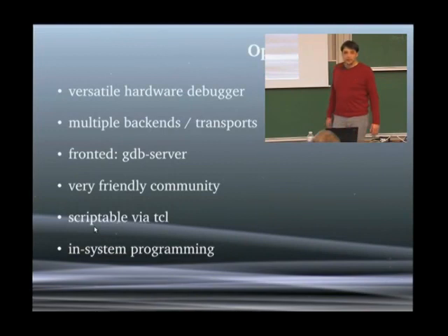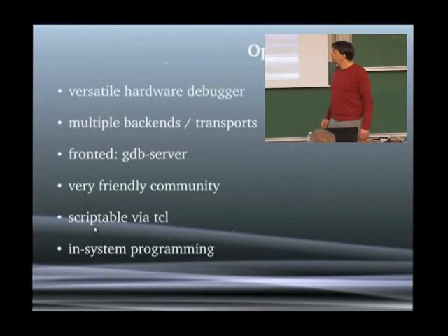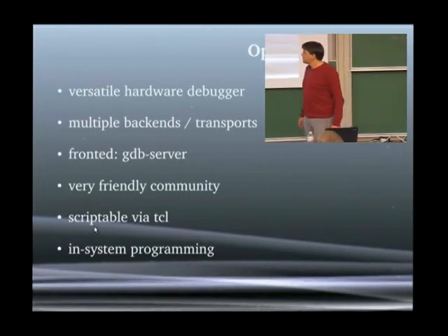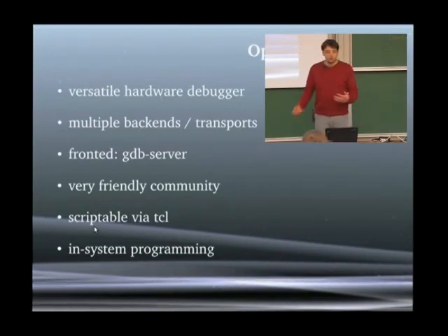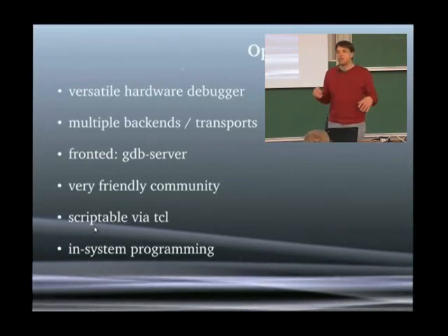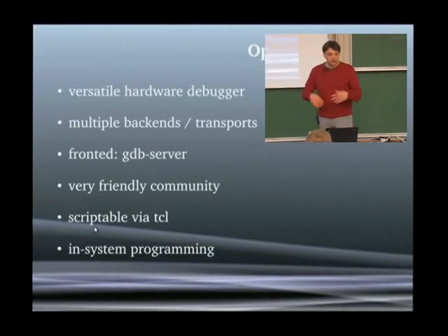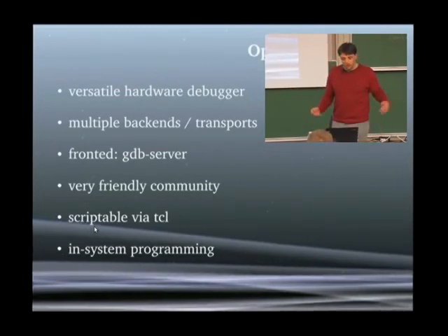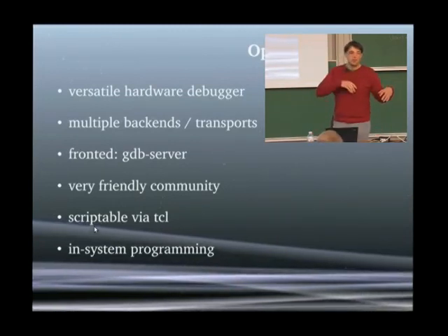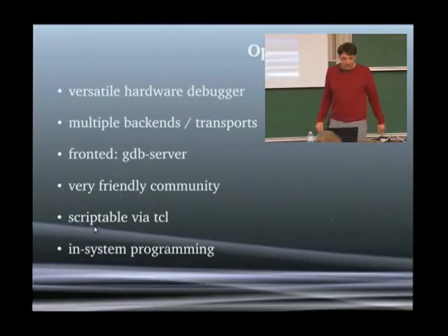OpenOCD's front end is a GDB server, so that's the way QtCreator is talking to it. The community is very friendly, and it's scriptable. You normally have to do some board-specific stuff, like how you do the resets, and you can script your own reset handlers if your hardware needs special handling, to make sure that it's coming up clean.